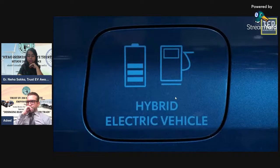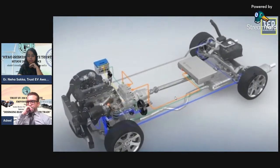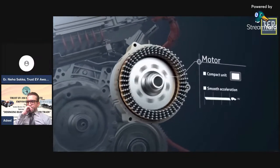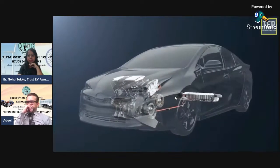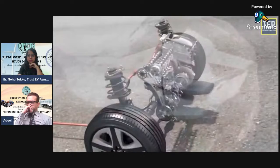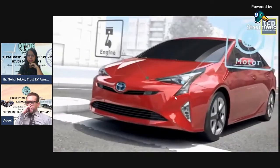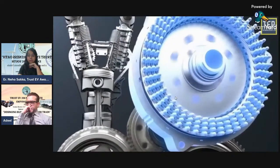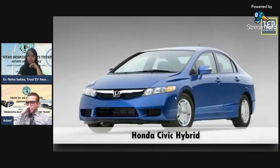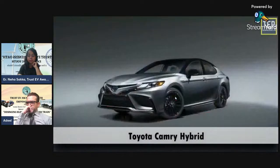Hybrid electric vehicle. These types of cars are often called standard hybrid or parallel hybrid vehicles. This type of car has both an internal combustion engine and an electric motor. In this, the internal combustion engine gets energy from the fuel, gasoline and other types of fuel, while the motor gets power from the battery. The gasoline engine and electric motor together drive the transmission, which drives the wheels. The difference between hybrid vehicles compared to battery electric vehicles is that in a hybrid the battery can only be charged by the IC engine, the speed of the wheels, or a combination of both. There is no charging port, so the battery cannot be recharged from outside of the system. Examples of hybrid vehicles are Honda Civic Hybrid, Toyota Prius Hybrid, and Toyota Camry Hybrid.